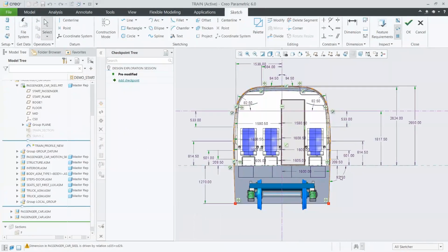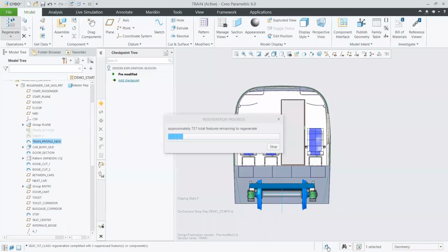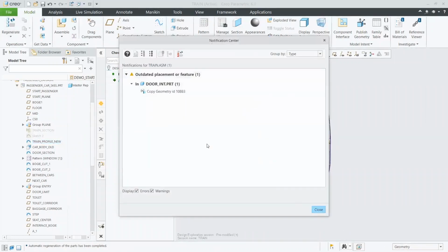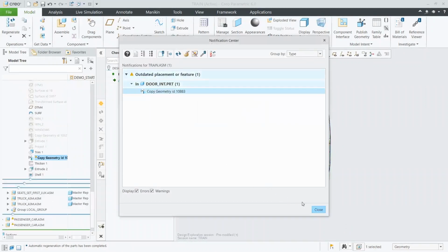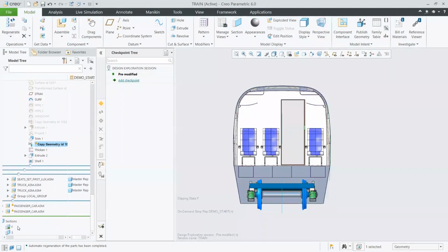And that's what we're going to do here, just go through and start to make some changes. Maybe we want to pull in the bottom of this and change the material usage. In this case, we'll just bring over that profile and change that skeleton. And what happens whenever we update? Well, essentially everything changes because it was all defined from that skeleton model. And that's exactly what I want in this case. Change everything around those walls. And notice one thing didn't change. That's actually because earlier we stated that we wanted this one to be a manual change with notification.